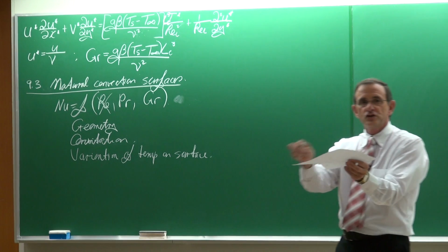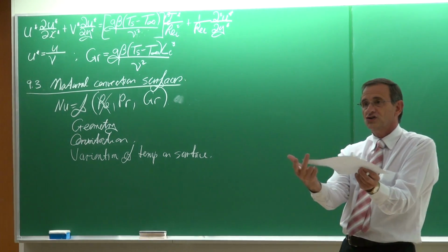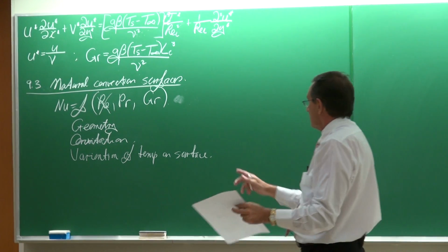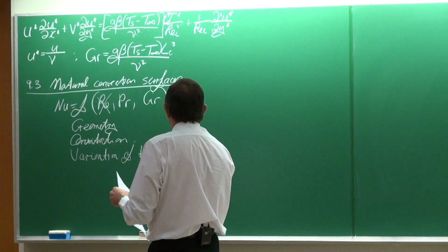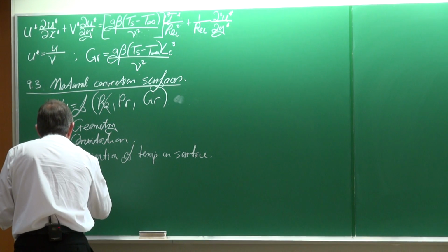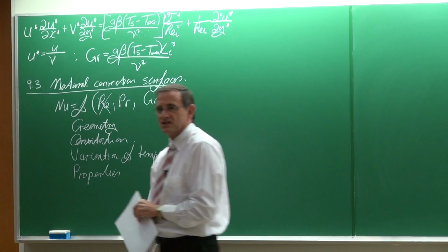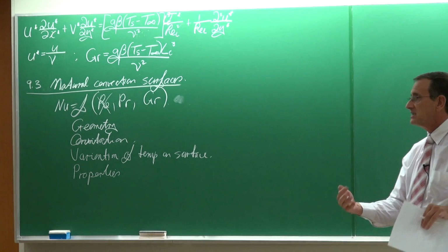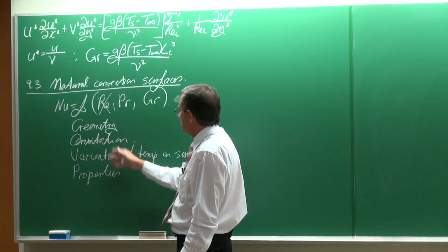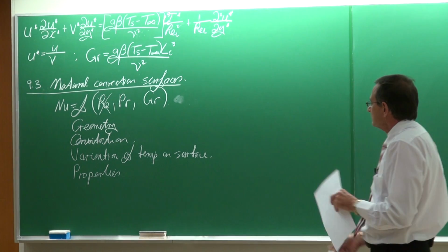So is it a surface where it's a constant wall temperature, or is it a surface where there's a constant heat flux, or are there changes in the temperature? That plays a role. And specifically, this temperature influences the properties, the thermophysical properties, the thermal conductivity, the viscosities, etc. All of that is specifically being influenced by this temperature or the representative temperature that we should use.